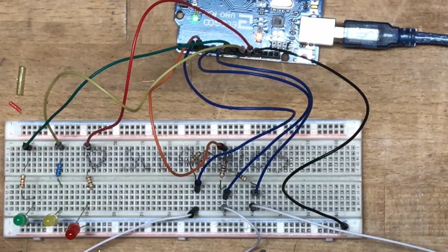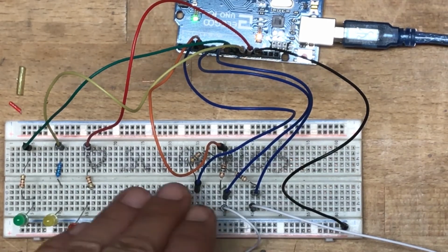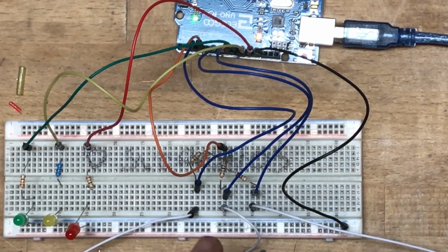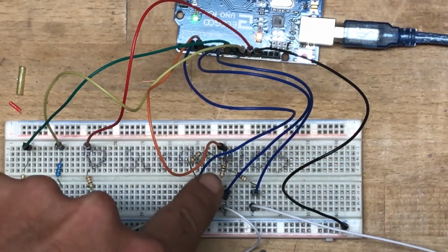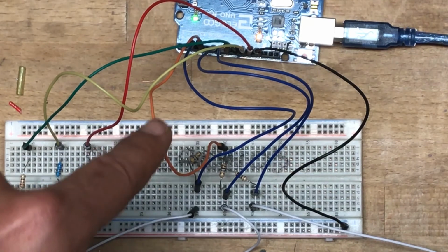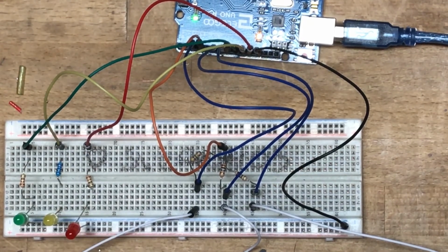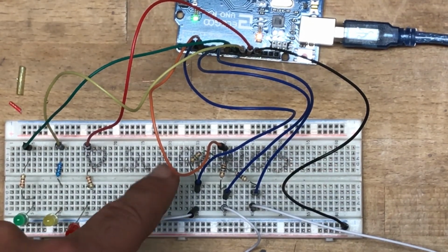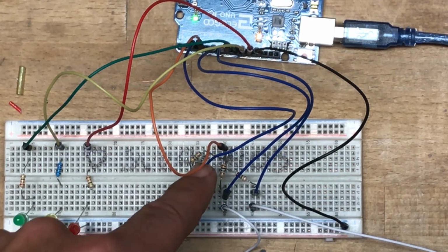So you could be doing this with a 2K resistor or a few resistors in series to up their overall resistance. Whatever you want to do, set those resistors up with whatever components you have. They're all sharing one row, which is going back to the board with this orange jumper. I believe that's pin 4, yep. So each side of each of those resistors is connected together.